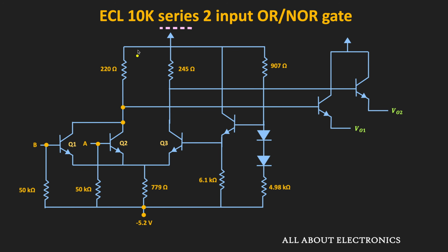So that is why for the current steering as well as for generation of the reference voltage, the separate ground is used. So of course, externally, when we connect the circuit to the ground, then all the grounds will get common. But internally in the design, they are kept separate to minimize the interference.